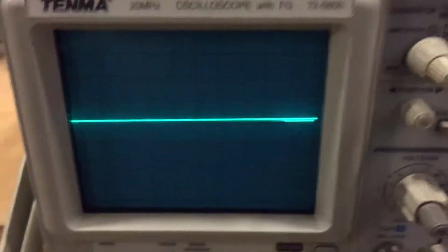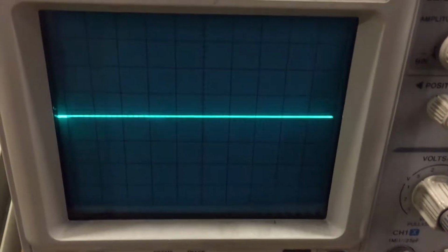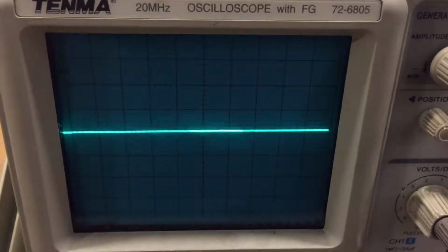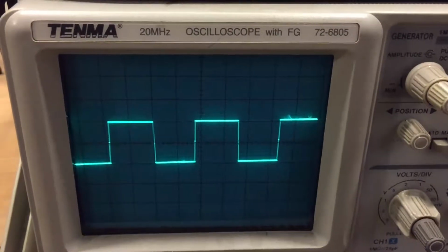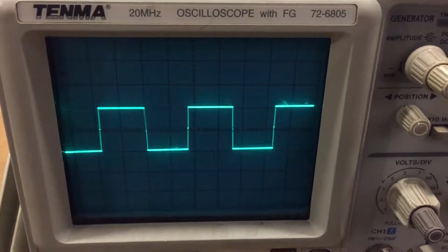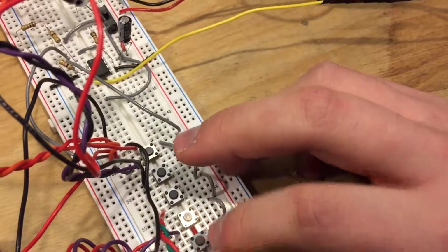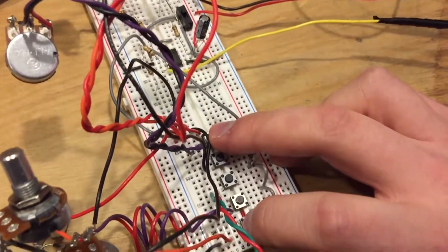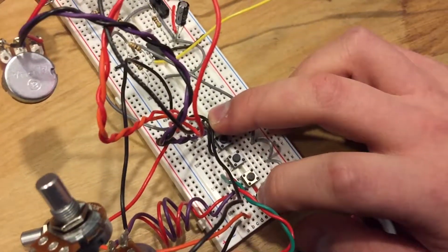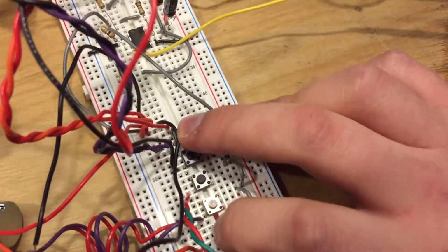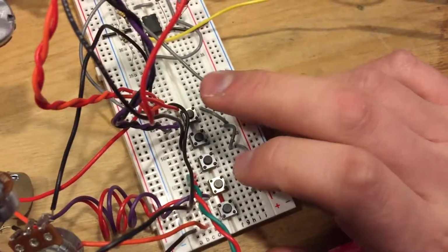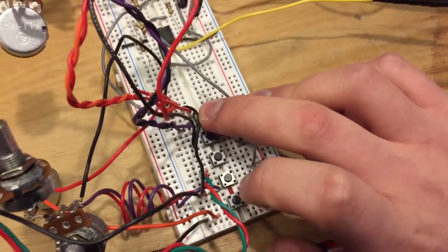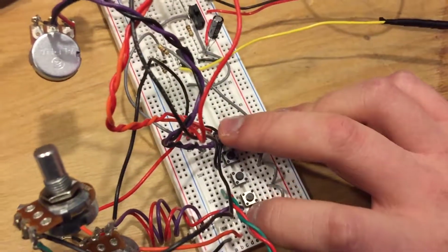Now if we go between the fundamental and the perfect fifth plus an octave, which is the fourth button, or the second to last one from the top, there is an even greater change. If we then go all the way between this button and the topmost, we should see a fourfold increase in the number of periods per time division. That also means that the output of this button is 2 octaves higher than our fundamental.